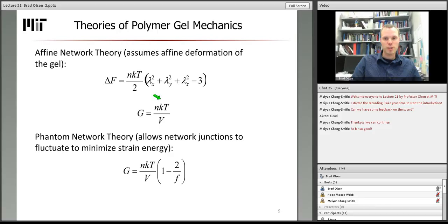So if you increase the molar mass of the polymer in terms of grams per mole, and keep the mass concentration the same, then what you're effectively doing is decreasing the moles of polymer strands per unit volume. And so a network with longer polymers will effectively be softer at a given polymer concentration, which again is consistent, I think, with what we intuitively know from polymer science, from the theories of stretching individual polymer chains.